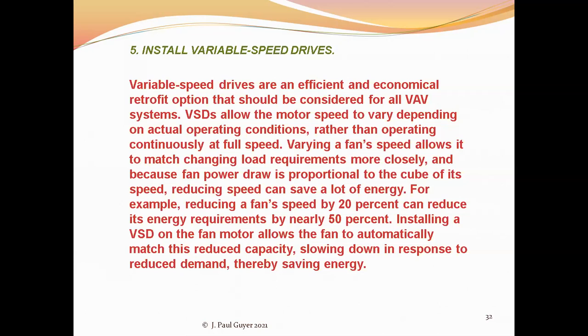And so if you have a mechanism for sensing when that condition exists, you can then reduce the speed of the fan so that it is passing through the required reduced quantity of air.